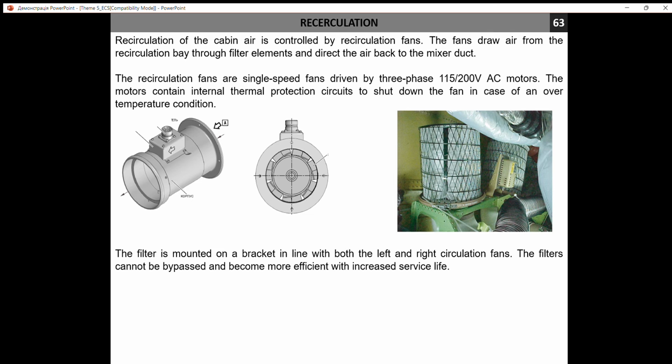Filters are so-called hard time elements. Hard time means that it is limited in its time and periodically it must be replaced. Depending on the type of the airplane, it may be from 1000 to 3,000-4,000 flight hours.